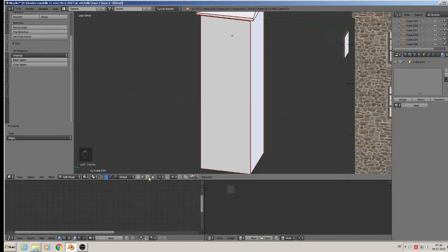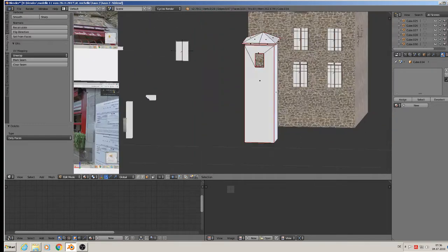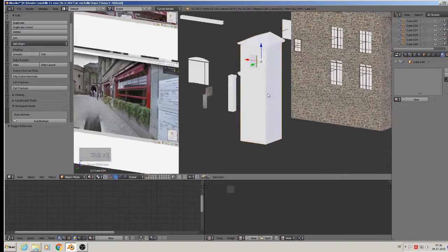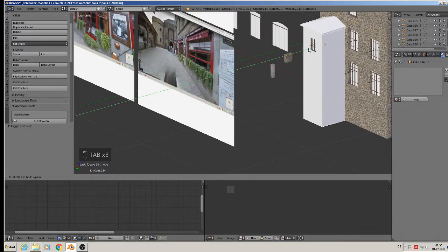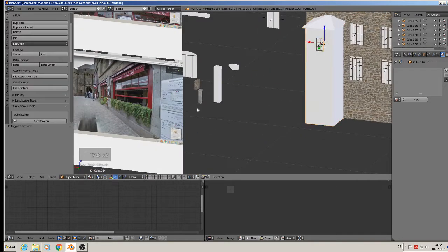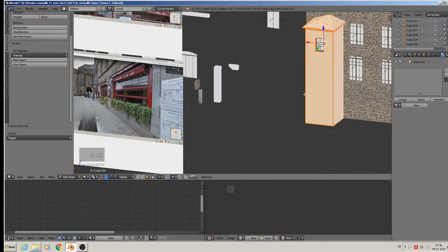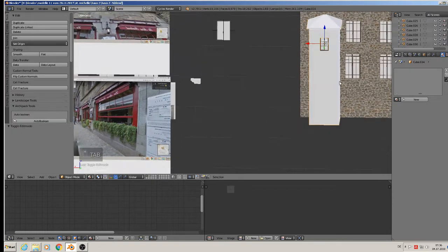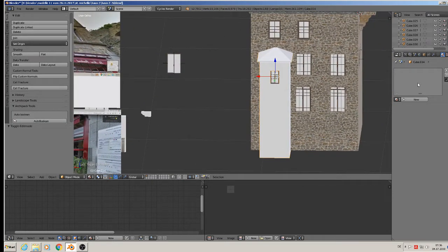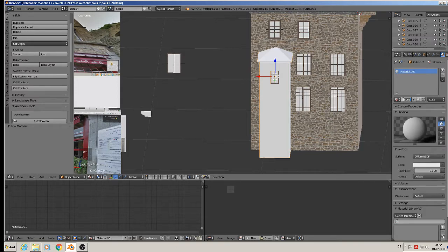That here we can open up, so only faces. Good. We've done that. Bring it on to. Then we have to object apply the rotation scale. Then we make here an unwrap. Then we give them the materials. That is, the first is the stone thing there. So we call it Little Tower House 3.